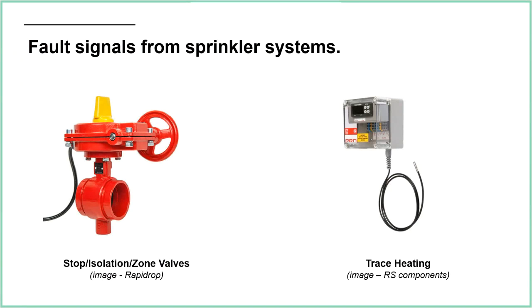So almost all isolation valves should be in the open position at all times. You can see that this valve pictured looks to me like it's currently in the closed position, because the indicator, the yellow blob on the top, looks like it's perpendicular to the flow of water. So that will be in the closed position. But I say most of them should be in the open position. The only exception to this is the bypass line on a life safety alarm valve, which is normally closed.